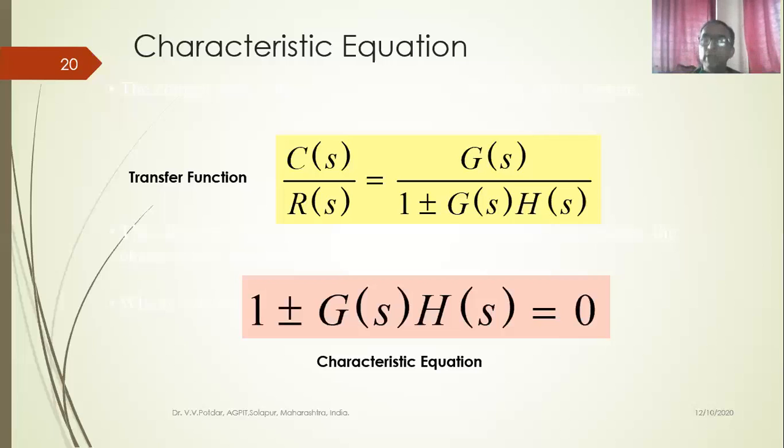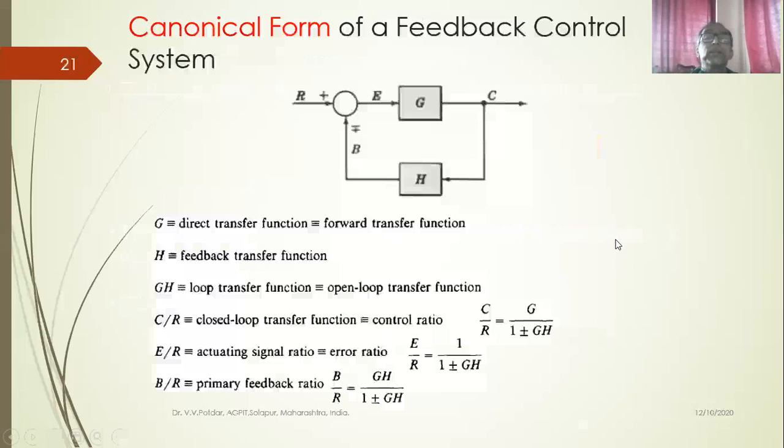So, in other words, we are predicting the system behavior before building the system, just from the equations of operation of that system, from the mathematical model, from the transfer function, from the characteristic equation of that system. I can suggest to the designer the range of values of various parameters related to different components. So this is why the name characteristic equation is given to this denominator of the closed loop transfer function.